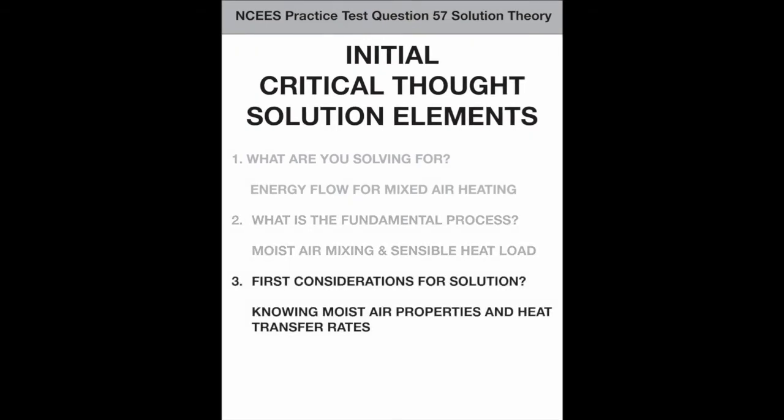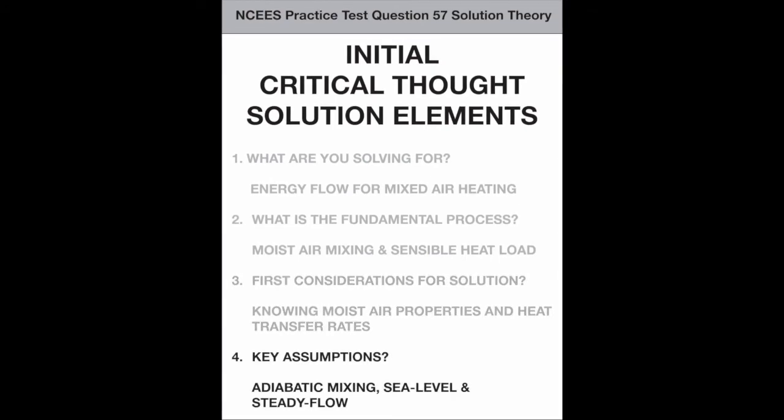3. What are the first considerations to find the solution in connection to the fundamental process? Knowing the properties of standard moist air and how they affect heat transfer rates. 4. Are there key assumptions? Adiabatic mixing, sea level conditions, and steady flow.